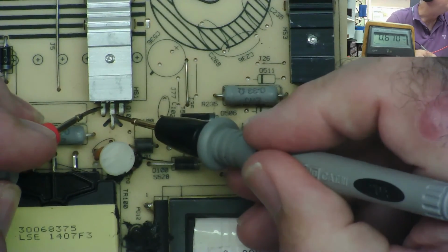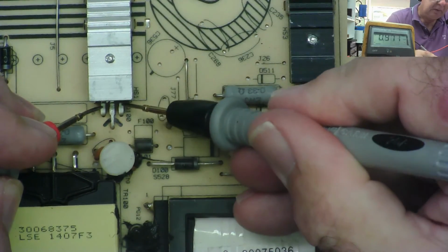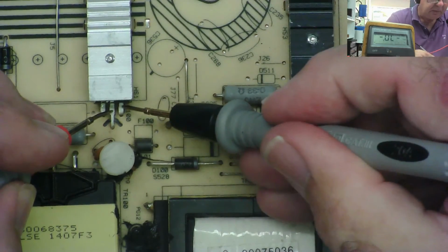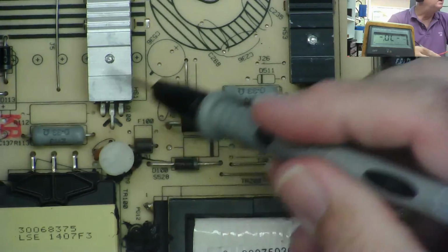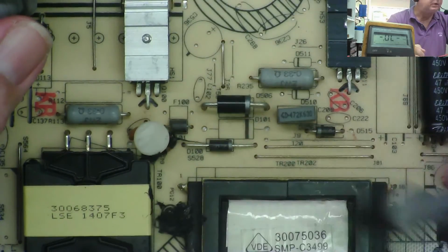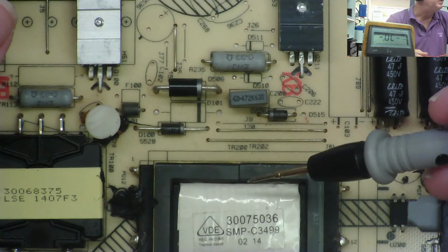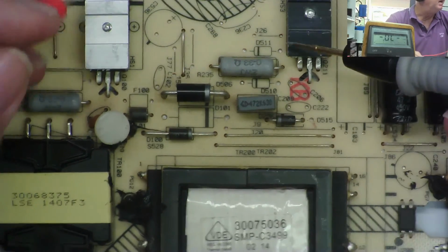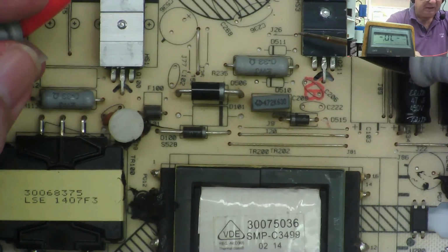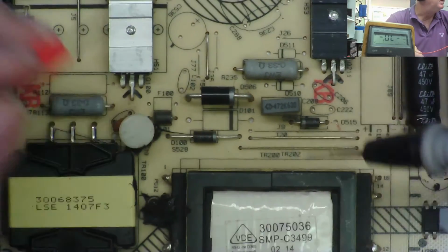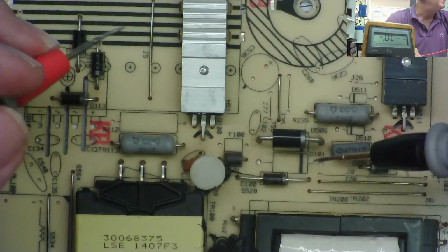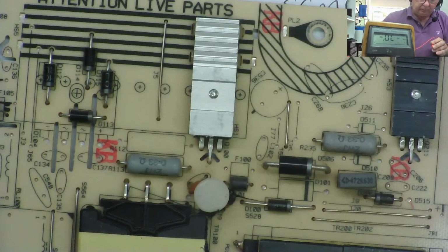Another one. 493. 528. Reads like that one's probably the same sort of device. Not sure. When you have transistors near to coils, it's quite possible to read what look like shorts and they aren't. So that's something to bear in mind. If it's near to a coil, you might read like a short circuit base emitter and it isn't. You're reading the coil. And obviously the coil is only a short at DC, at AC it isn't. So that's those ones.